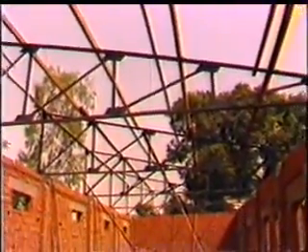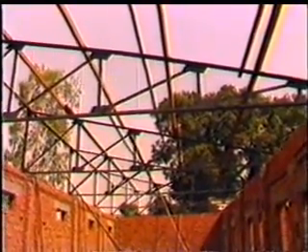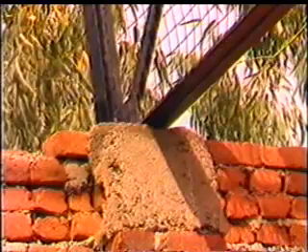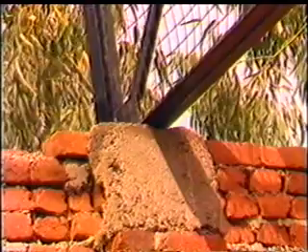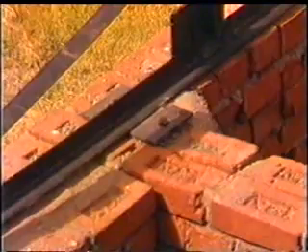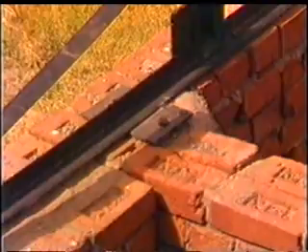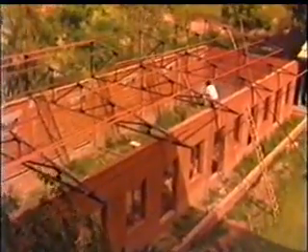The trusses are erected and fixed to the supports. Trusses are fixed on the walls and columns by means of anchor bolts which are connected with the base plate attached to the bottom chord of the truss. Trusses support the purlins at suitable intervals on the principal rafter, and they are connected by cleats.